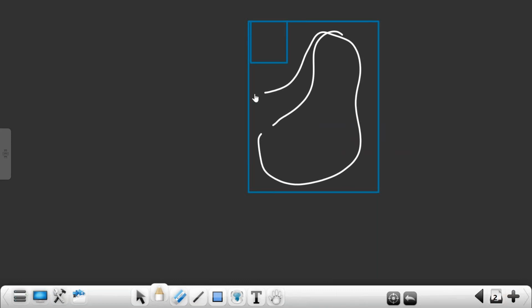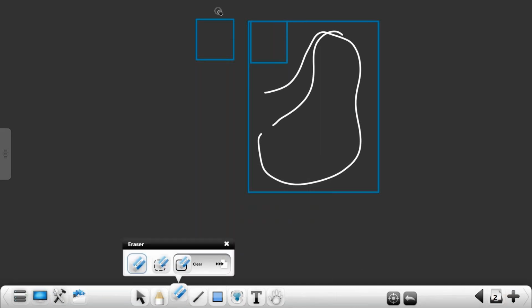But when I do cell-based design, my design is this much, which means I can create an IC only for this much area, which can be optimizable. Optimizable means I can improve the design. Because after I give the GDS file, the foundry will fabricate on top of that. But FPGA is not like that. They have already given it, you cannot do anything. You use whatever you want in that. The remaining thing will be what? Wasted. It's not optimizable.